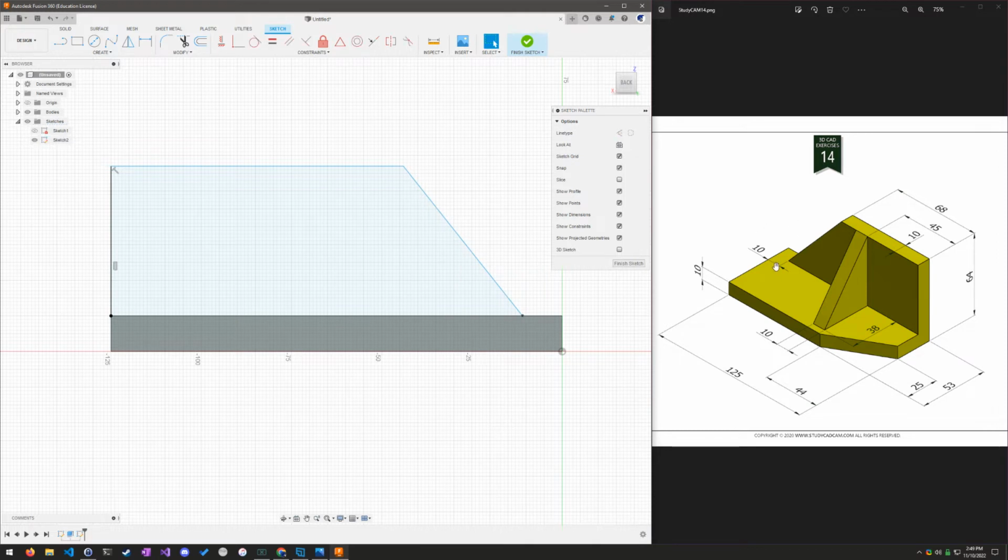All right. Now, this black dot is 10 millimeters from the edge of the piece, so I can do that as well using my dimension tool. The height from the top to the bottom is 64. That's important. This line is not 64. This line is 64 minus 10.